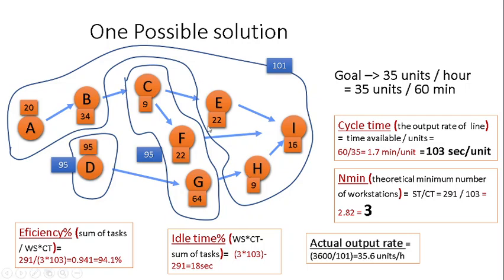And why is that happening? Because as you can see here, the theoretical cycle time is 103, but in reality, we have 101 seconds as our cycle time. So we have gained 2 seconds from the theoretical. Well, in reality, of course, ideal situations are rare, so we have to count for some breaks. We should not look for 100% efficiency, but a little bit lower, because in real life any type of problems might happen. So we have to provide some buffers to our operations.